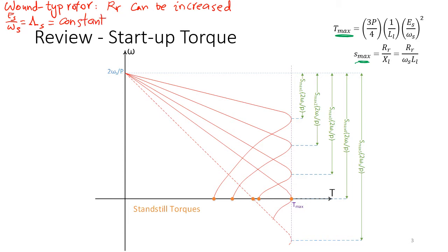In fact, as we said, to have the best performance, in most cases we want to keep gamma s high at the rating, but we cannot force it and push it to be more because it gets the machine saturated. So you will see this more, that we try to keep gamma s constant, or at best we decrease it. We rarely, if ever, push it to increase, because it may saturate the magnetic material that we have used inside the machine.